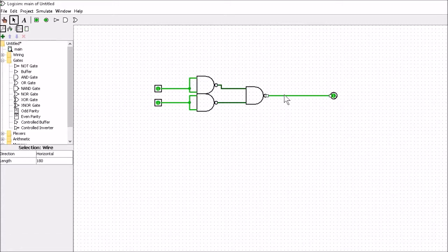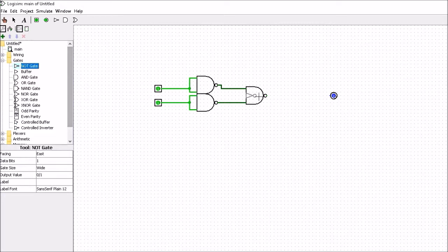So I could take another one of these NAND gates and tie the two together and put it as an output, but we don't need to. We could just put in this realization here. It's the same thing. So now we've got a NOR gate using what would be 1, 2, 3, 4 NAND gates. So let's go ahead and check whether this actually works.